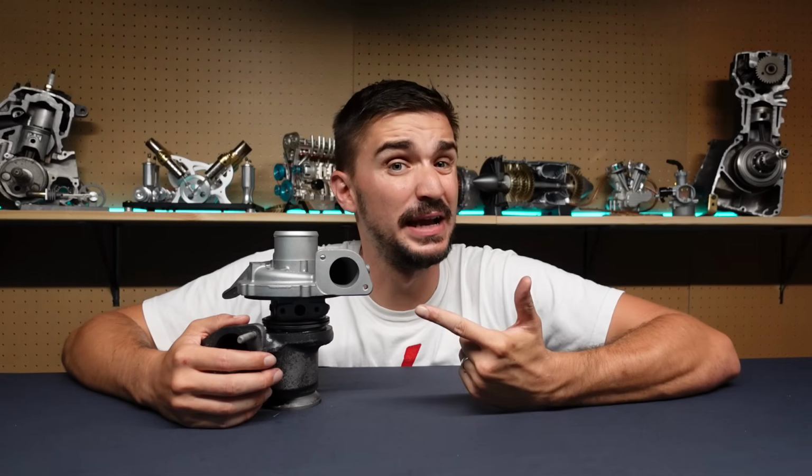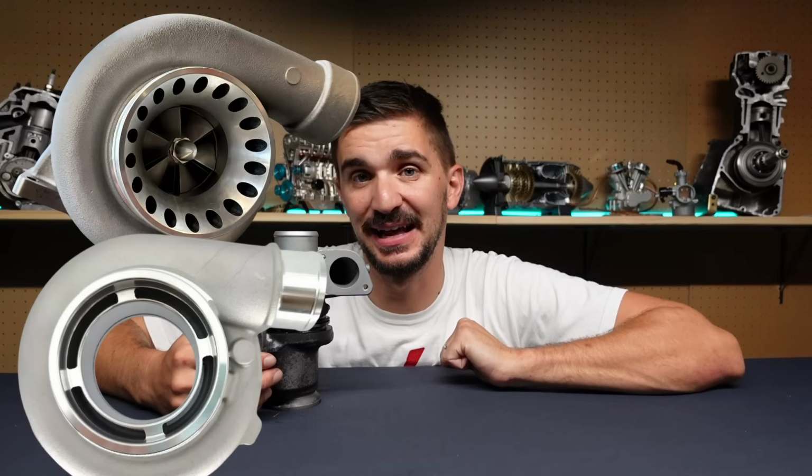To get rid of surge that occurs when you press the throttle pedal, you can either reduce the boost pressure or install a smaller turbocharger. Something else that can help is an anti-surge housing like this one, which has these ports, which basically act like an escape path for the reverse pressure wave, so they can eliminate or at least reduce compressor surge.